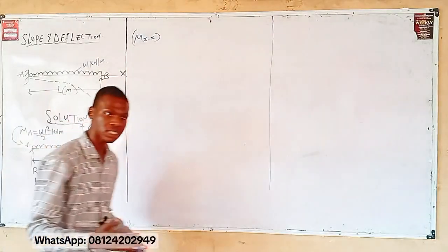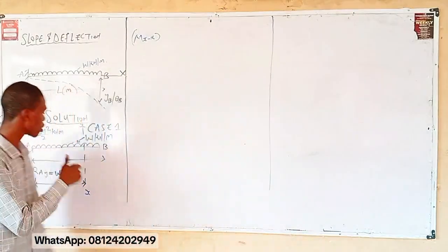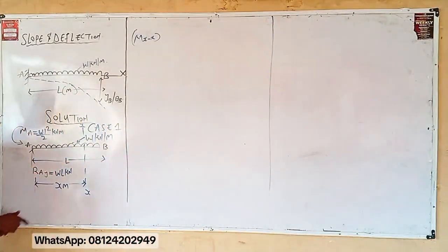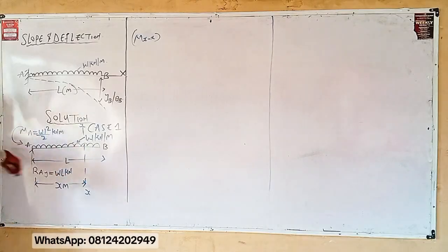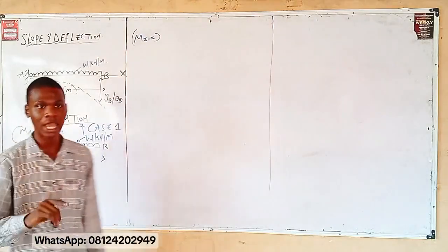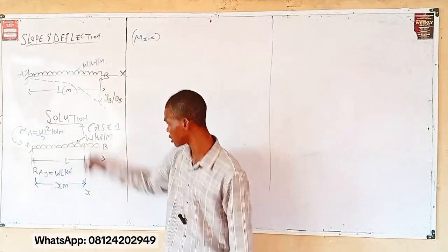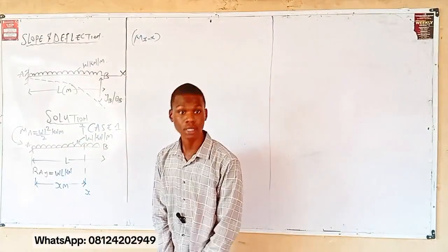What's the idea of moment? The same way we took moment calculating the support reaction, take your moment that same way. So let's say you are taking moment about this point. Meaning all the forces are going to what? This line you've sectioned. Now identify how many forces do you have? Meaning how many forces are there going to this section part? 3.